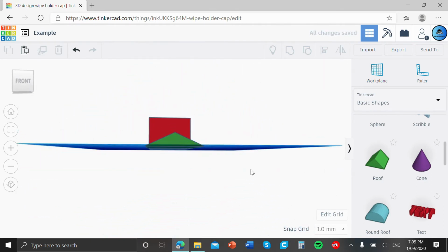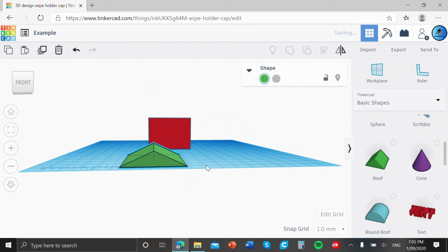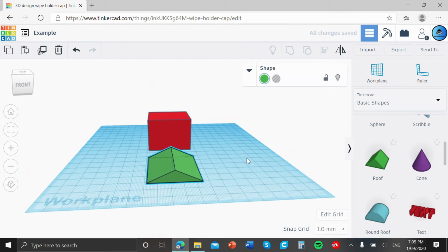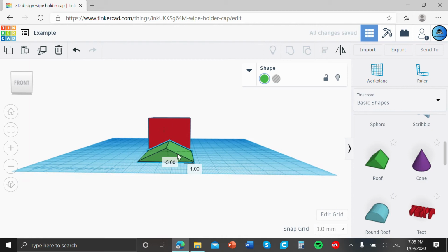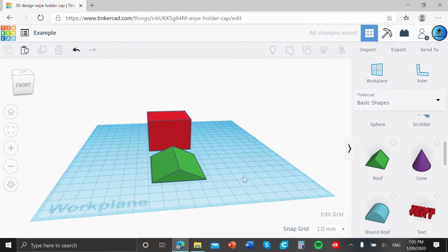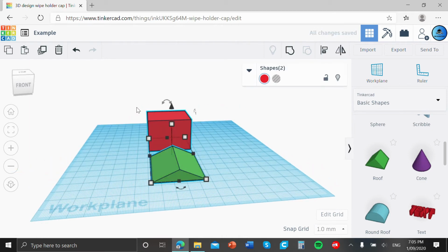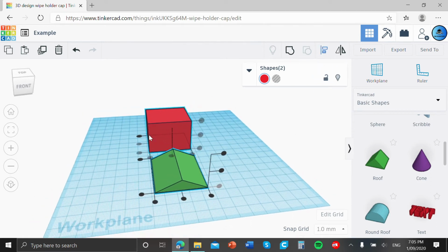Say you have it like this and you're like, oh, I don't know if it's straight or not, I'm just going to eyeball it and see if it looks aligned. What you have to do is select and click, and then go up to here and press align, or for the keyboard shortcut just press L, and then you'll have these things that come up here.